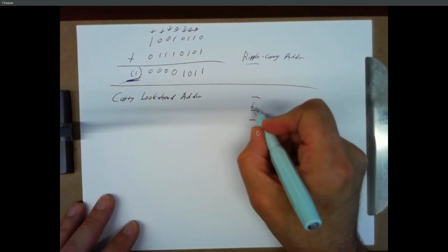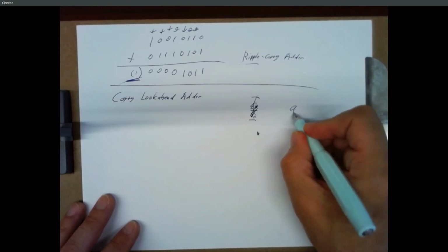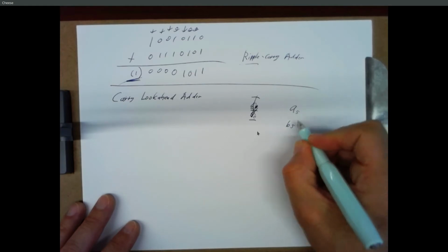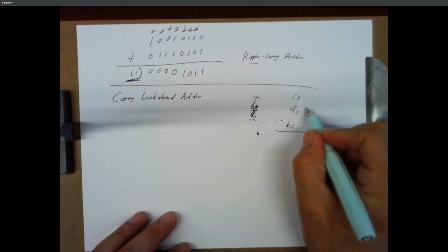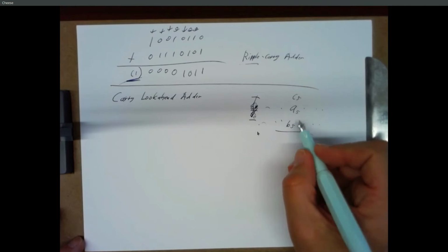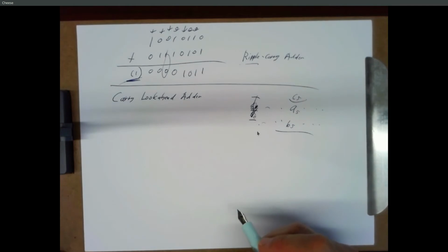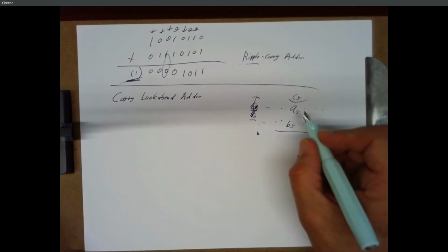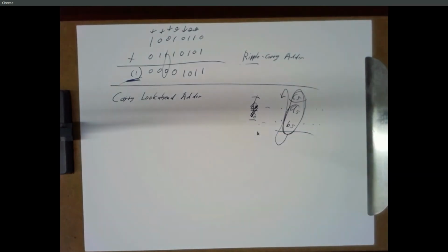Basically, we've got some part of our addition that we're performing. Let's just look at bit 5. So we've got bit A5 and bit B5 that we're adding up, and we've got some carry that we're also adding into that, which might be a 0 or might be a 1. The question is, when does this addition generate a carry into the next stage?